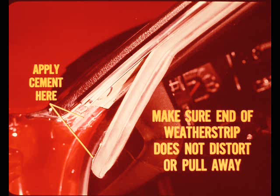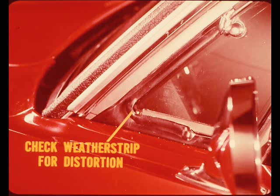Incidentally, if you install a new weather strip, make sure it is correctly positioned by lining up the index notches in the weather strip with the locating tabs in the retainer. Also, check the vent wing weather strip for puckers or distortion, especially at the front lower corner. This type of distortion can be caused by the glass moving out too far due to regulator over travel.